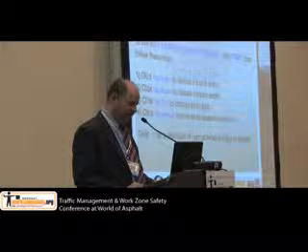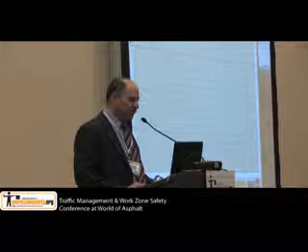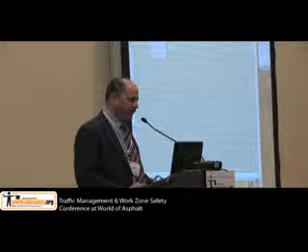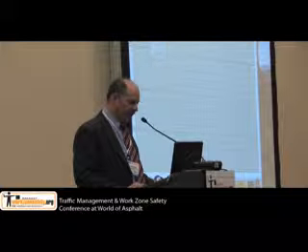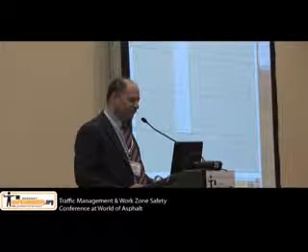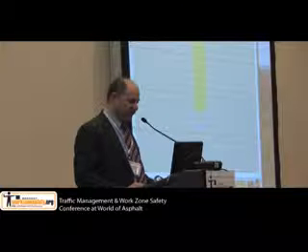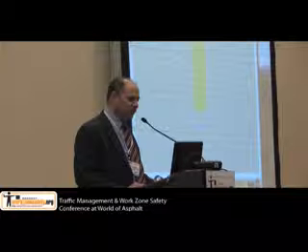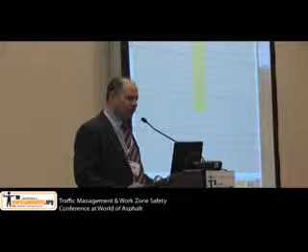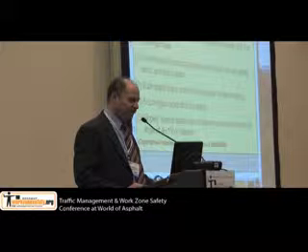So if we click the Start button, for example, we can set the width of the excavation. Say we make it 4 feet wide. Say we make it 12 feet deep. Okay, and we set the soil type. Say it's type C soil. And you can click this little question mark to see what that means.